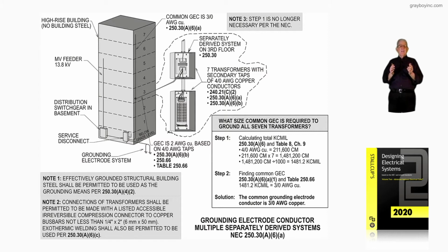And we would have isolation receptacles at the locations fed from the circuit breakers in the panel board. And we wouldn't want to pick up noise or antenna type effects, unwanted noise that sensitive electronic equipment on each floor would sense and malfunction.